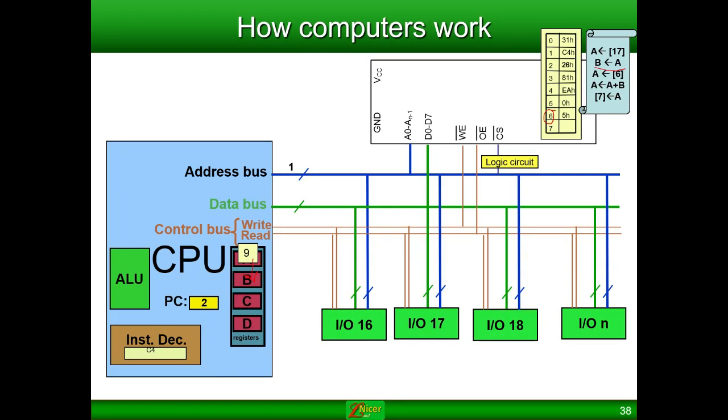So here it's simply going to move the data from register A to register B here, and it makes a copy of the register data which was stored in A. And as we can see as well that our program counter moved to 2. So now we will see that our computer will give the address of 2, and we can see that on address 2 we have 26 instruction. So this instruction is going to go towards our CPU. Our CPU is going to decode this instruction.